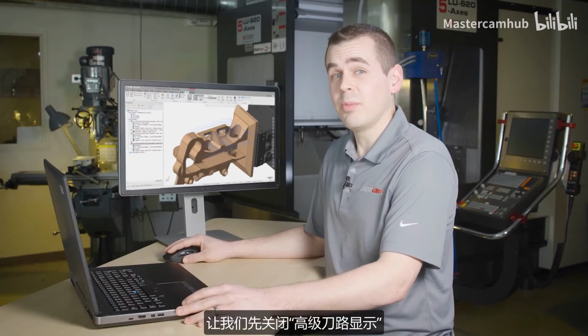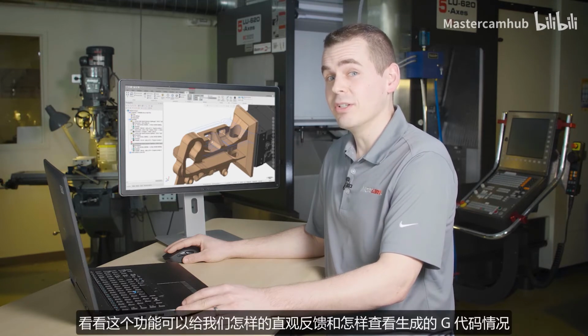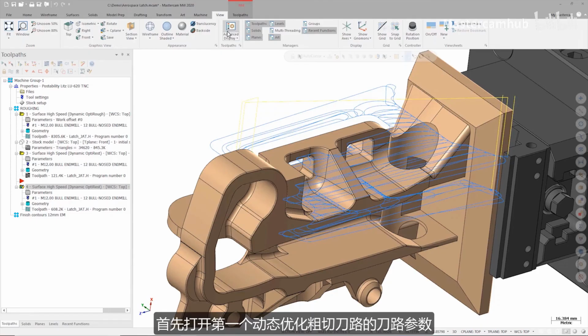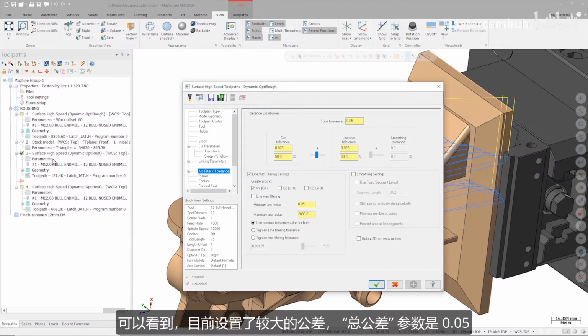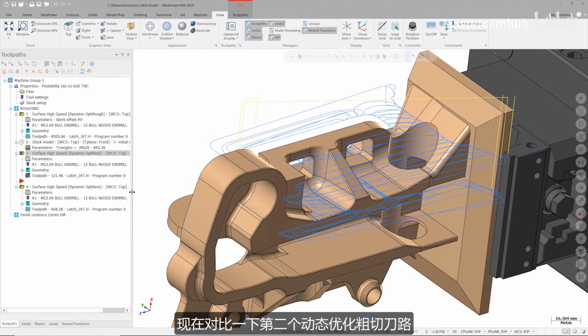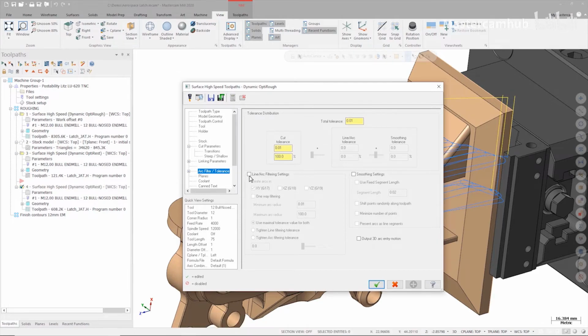Let's turn off the Advanced Toolpath Display and look at a real-world application of this function and how it can be leveraged to get some visual feedback on how the G-code is going to look. To do this, let's open the parameters of the first OptiRest operation and look at the arc filter tolerance parameters. Notice I have a fairly loose 0.05mm total tolerance and my arc filter is turned on. Now let's compare these settings to those of the next OptiRest toolpath. I have a much tighter tolerance here and no line arc filtering is turned on.